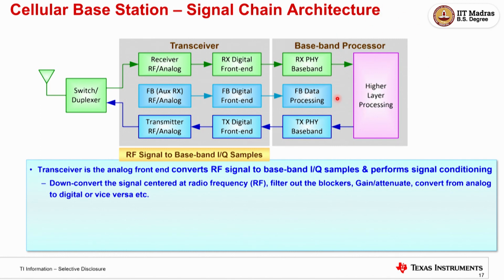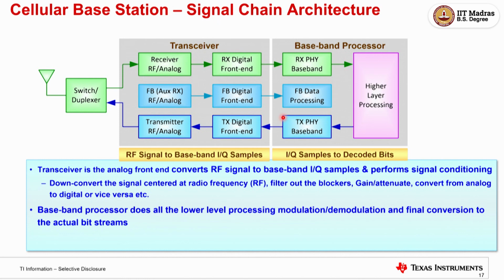So that's a baseband processor. If you take a cellular base station, there are two units. Usually they are called the radio unit, which is the transceiver, and then there is the BU, which is the baseband unit, right? These are two different boxes. Usually they make two boards. So this is all DSP, signal processing that you do in a processor. This is all analog, right? So the baseband level is all in the digital domain.